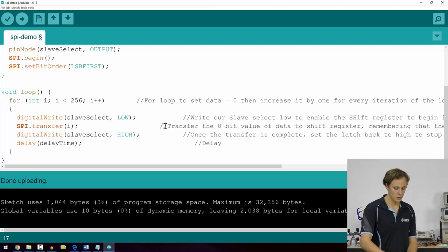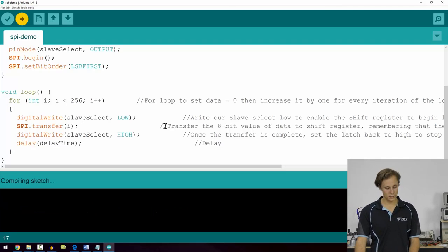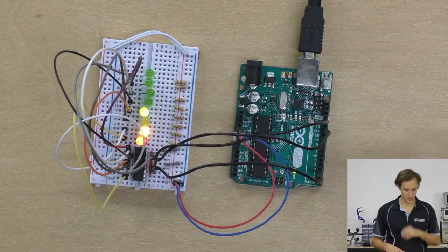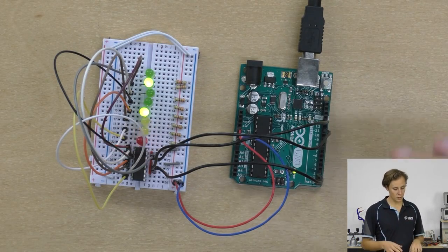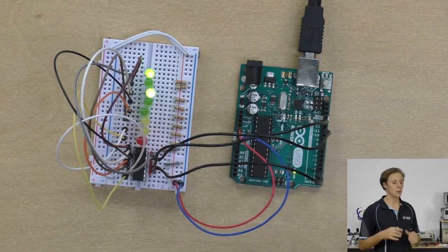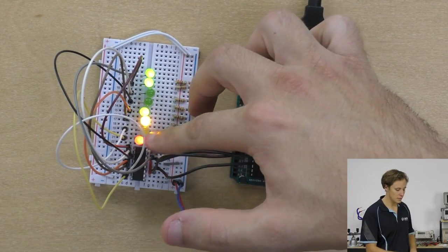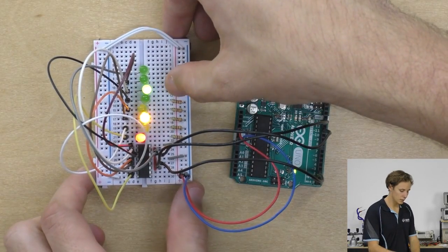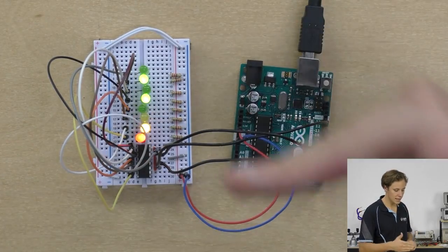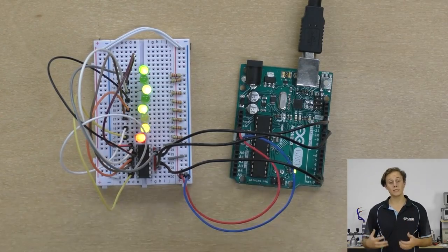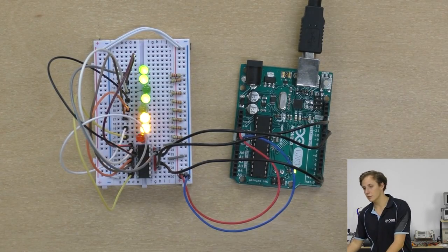Connect your Arduino to your computer. I've already got this uploaded, so ignore the fact that the program starts up automatically. So it'll go through and compile, upload, and you can see that that's done uploading. So now that it's running on our board, you can see the binary counter, it's incrementing. You can see that fairly well. So it's happening quite quickly, and you'll notice that it shifts these LEDs up. Oh, that LED wasn't quite working. There we go. It shifts the LEDs sequentially along as each one before it fills up, which represents how the binary data works. So let's slow this down a little bit.